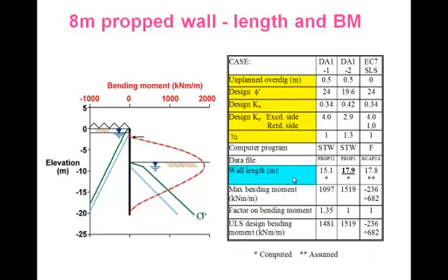When we do that, we calculate the wall lengths. We have to use the longer of the two wall lengths because we have to comply with both requirements, and in this case we'll normally find that it's combination 2 that'll give us the wall length and the biggest bending moment for structural design. We do the serviceability unfactored calculation, maybe using different software. We'd get other bending moments to consider for serviceability. So for crack widths, for example, we'd look at these lower bending moments.